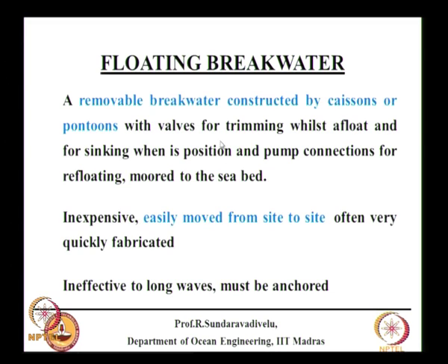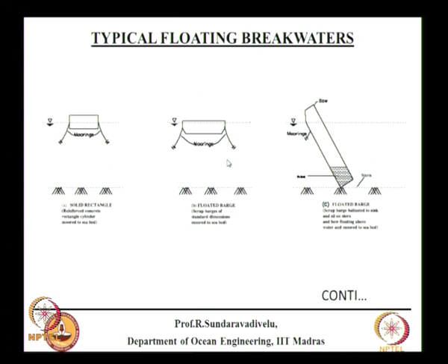That is, you can float it to a place, use the valves, sink it in position, and you can refloat also. They are inexpensive, easily moved from site to site, and can often be very quickly fabricated. This can be used for defense purposes also, but we do not use this because it is ineffective for long waves, and it also should be anchored. So this is typically a floating breakwater with mooring.